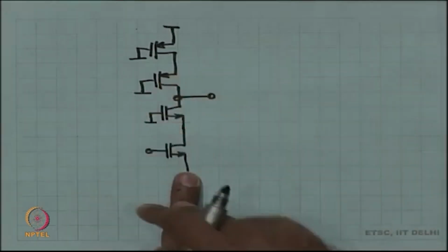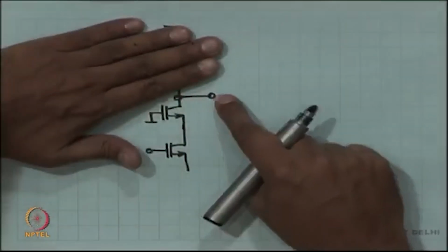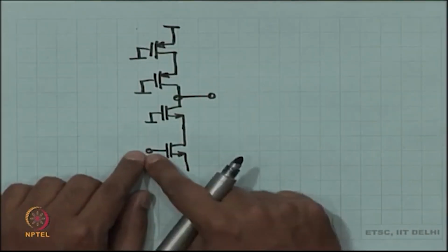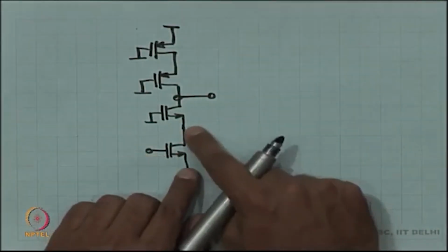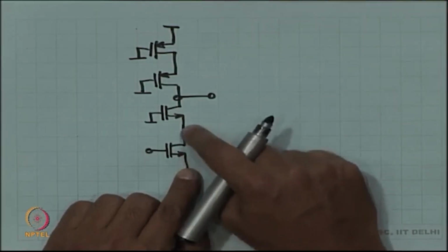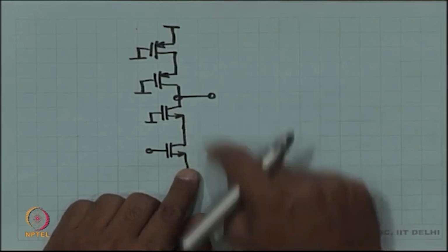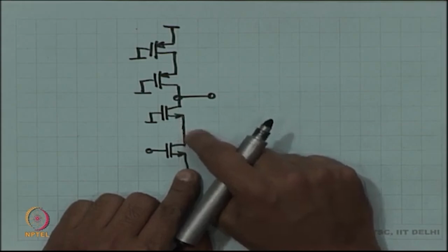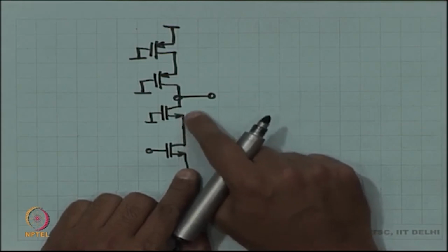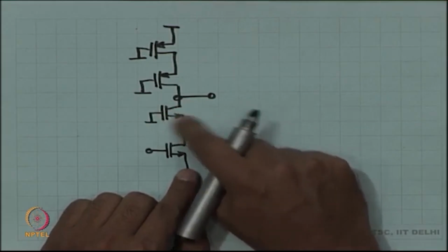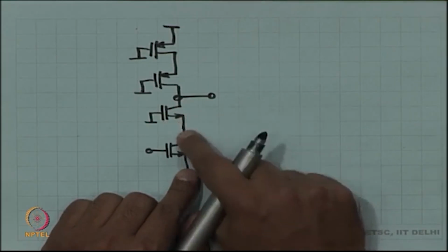So we are looking at short circuit current, right. In the short circuit current experiment, you have shorted the output. You applied a voltage here that created Gm times the current. This Gm times the current is trying to split between RDS and what you see looking into the source. Now, what do you see looking into the source? You see 1 over Gm of this device.